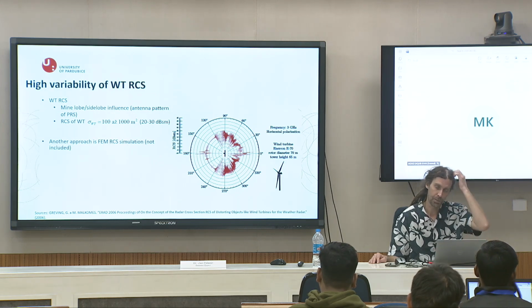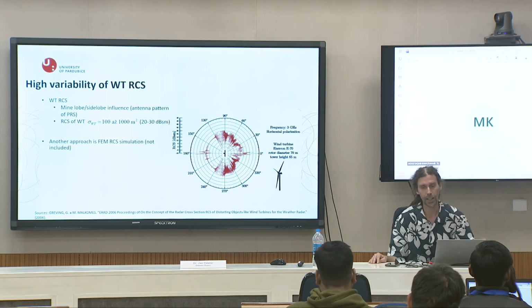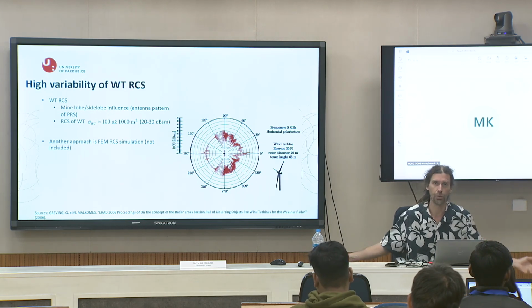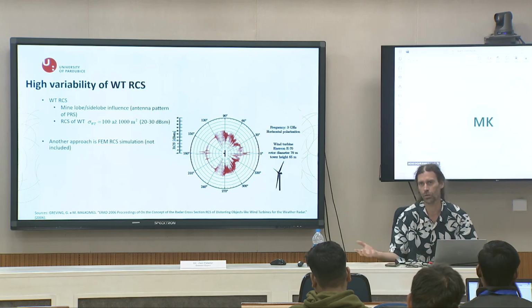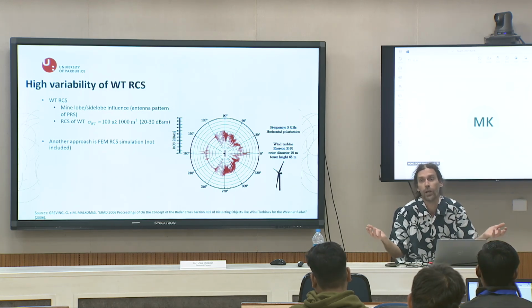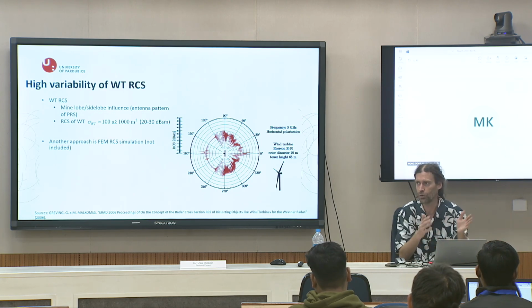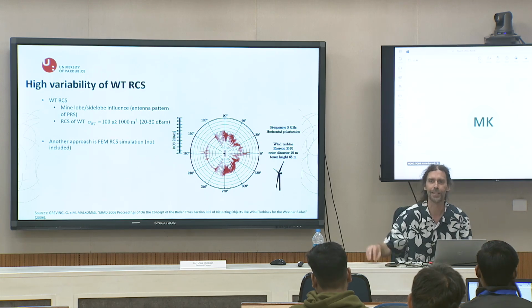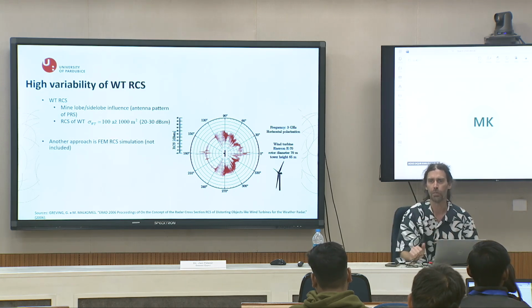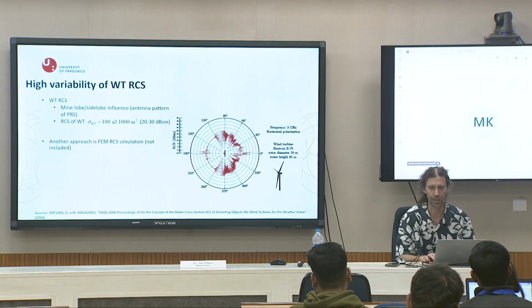Why can't you measure RCS directly outside? Because it is influenced by the environment, other signals that are in the environment, and so on. So you will not get it. Okay, you will get a measurement, but it does not mean that it is just the RCS. It is RCS plus many other reflections.